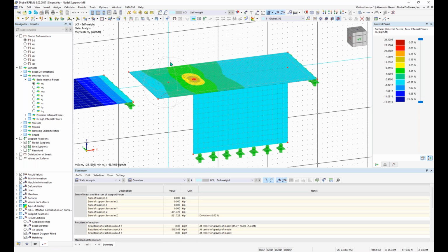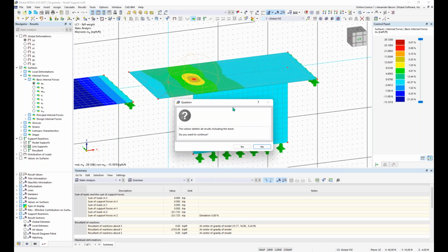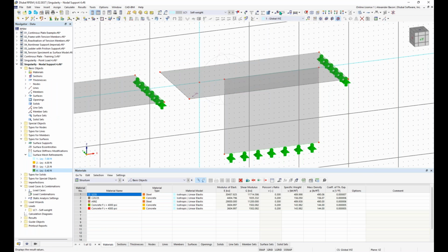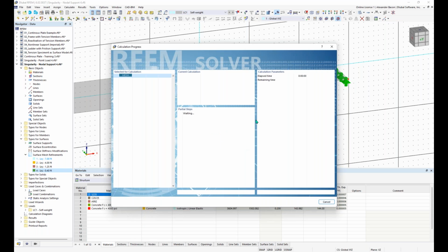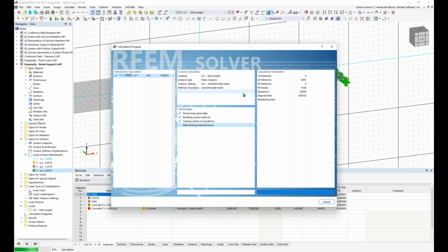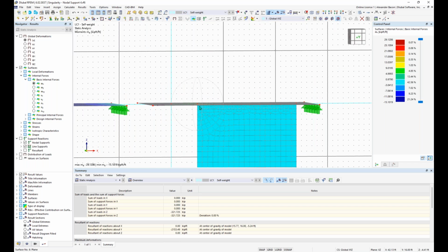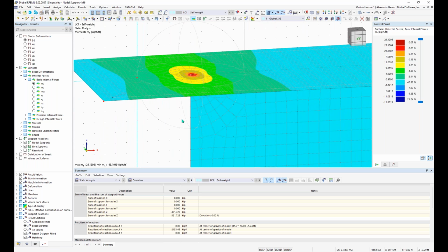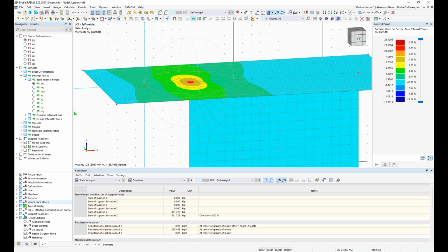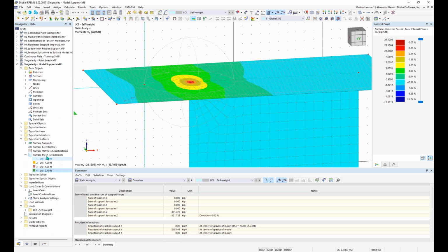What you can do is add an FE mesh refinement like this, which would help, but it would also help to just make the corner of this wall rounded just a little bit, so it's not just one single point feeding into an FE mesh node like that. And then also we have smoothing regions that you can apply to your surfaces here as well.